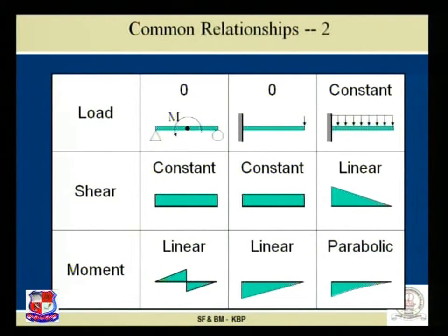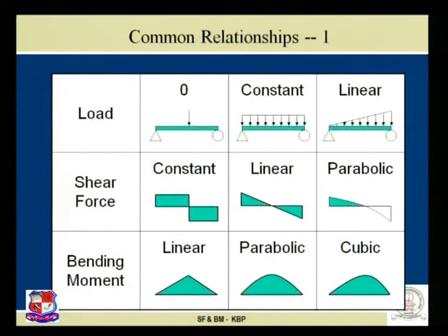Before we proceed further for a cantilever beam, remember from the previous slide that the bending moment nature shown is sagging throughout. So for a simply supported beam with any kind of loading, the variation of BMD is of sagging nature.